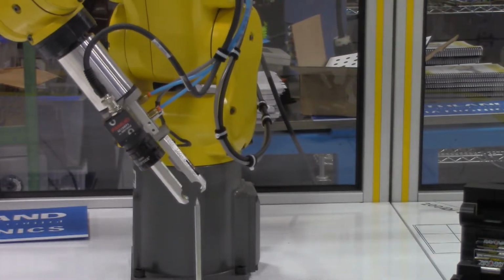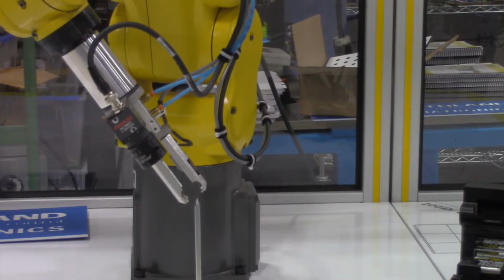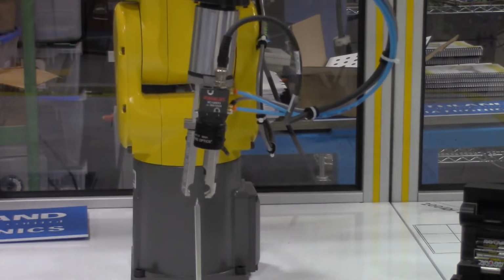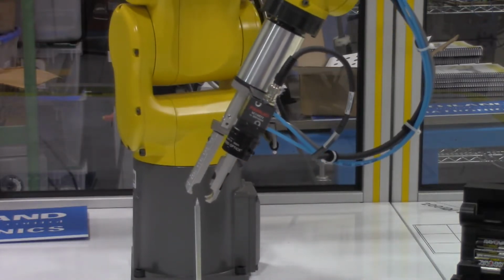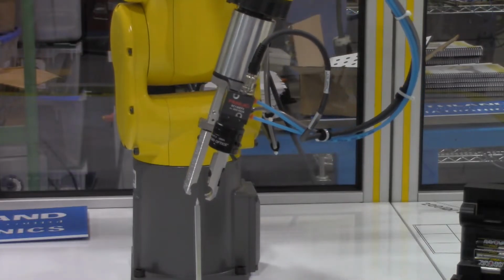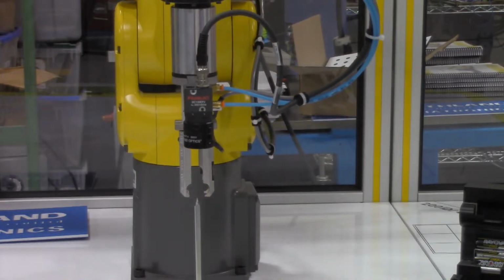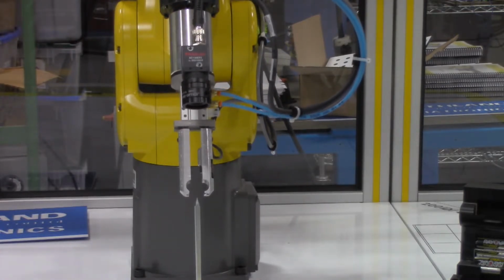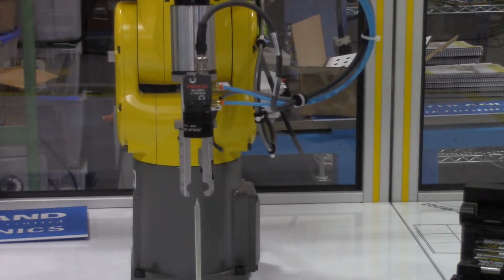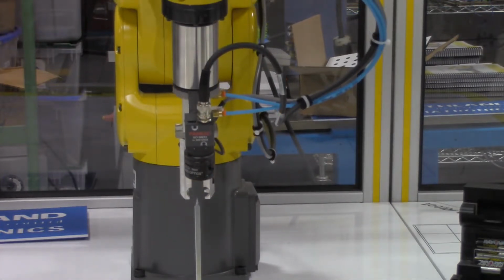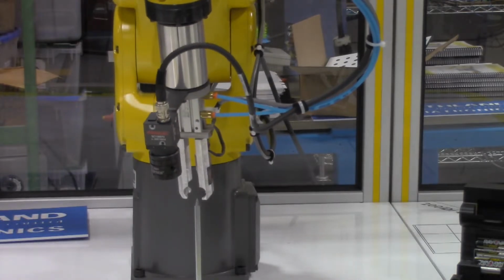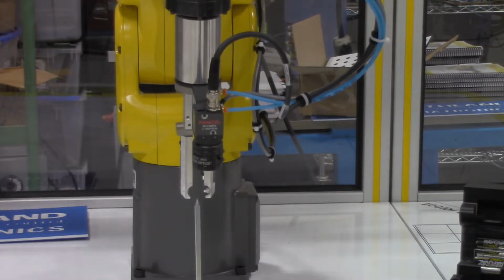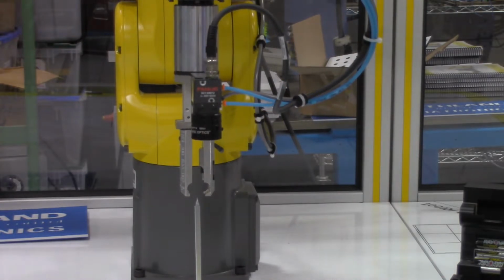Hey mechatronics students. In this video we're going to be talking about tool frames. This is a really interesting thing. I'm demonstrating the rotation of the robot, jogging it in world mode about the minor axes. And you can see as I'm doing this, the end of the tooling doesn't change when I rotate about the minor axes in space. This makes it a lot easier for the robot to pick things up and to jog the robot around and get to certain spots, and it kind of compensates for the end of arm tooling.